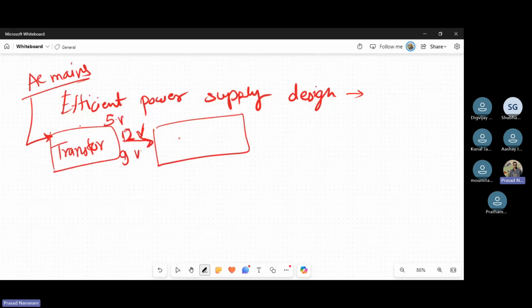So we basically rectify this signal. Okay, we polish this signal in PCBs. Okay, and on board itself you have this power supply design. We convert the power formats, and we get it to the proper format. This is nothing but the power supply design. We have the voltage regulator circuits in it. Okay, voltage regulator ICs maybe. So suppose these ICs are basically only 3-pin ICs.